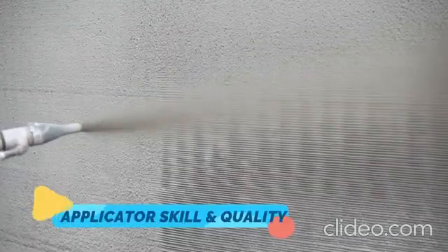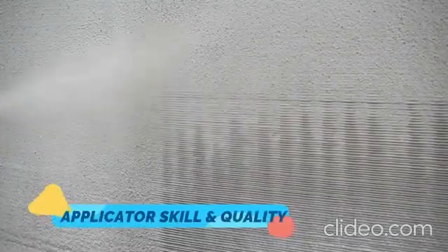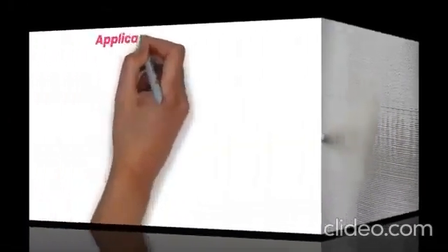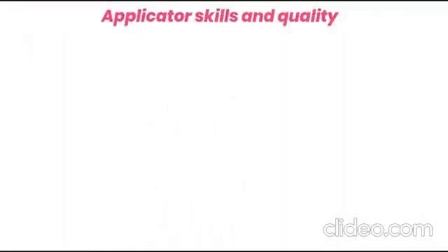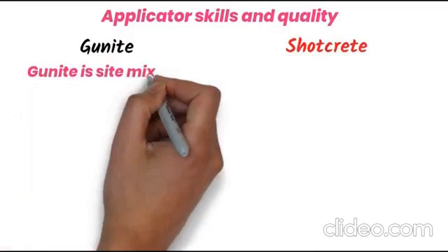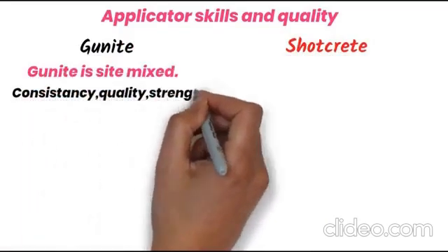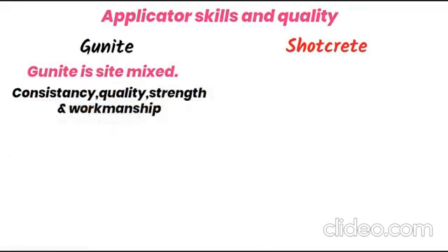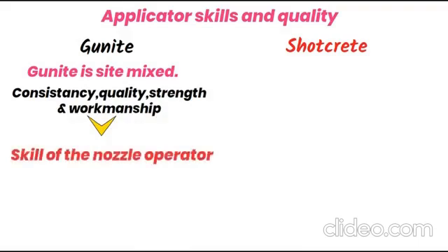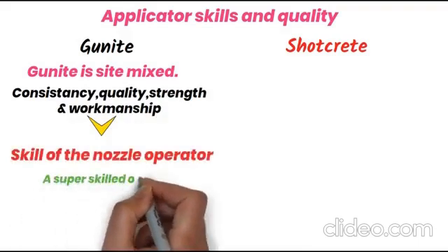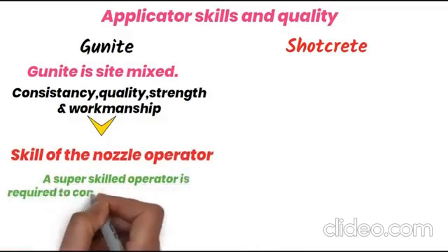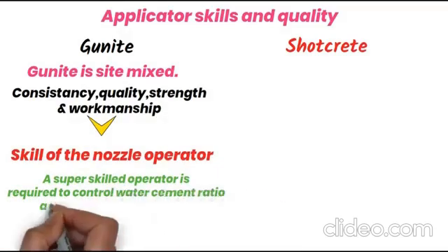We'll discuss the applicator skill and quality in case of gunite and shotcrete. Gunite is site mixed, and consistency, quality, strength and workmanship depend on the skill of the nozzle operator. A super skilled operator is required to control the water cement ratio and maintain consistency.